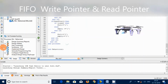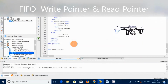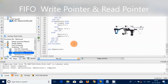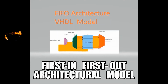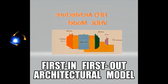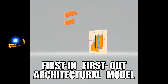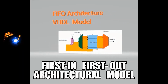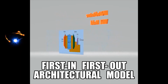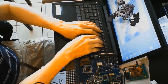In the dual port RAM model segment of the FIFO, a write counter addresses the write side of the RAM, a read counter addresses the read side of the RAM, and the control logic updates the write counter at each write of data into RAM, and the read counter every time data is read from RAM.